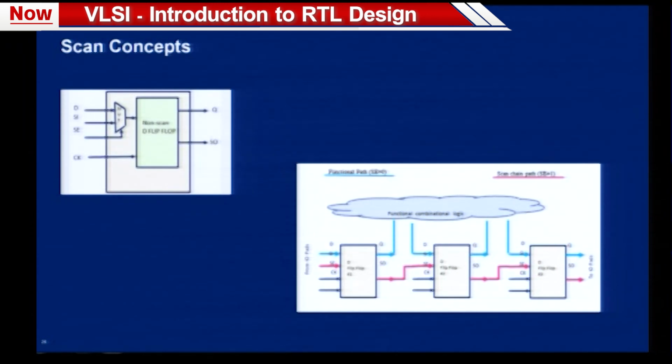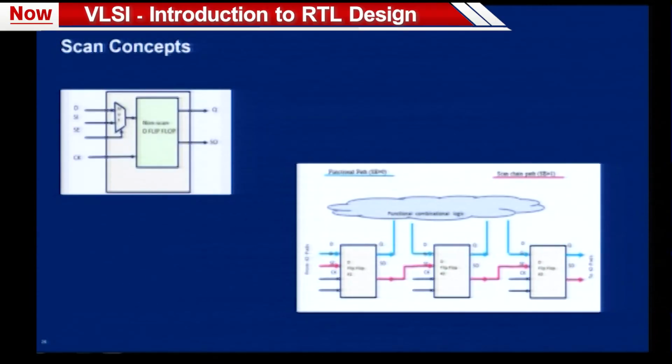The advantage of this scan chain is, if I want to insert a value at a specific flop, let us say some flop very deep in my design, I have a very direct path to that flop. I do not have to worry about what kind of combinational logic comes into the picture. From the primary scan input, I will go and reach directly to that specific scan flop.